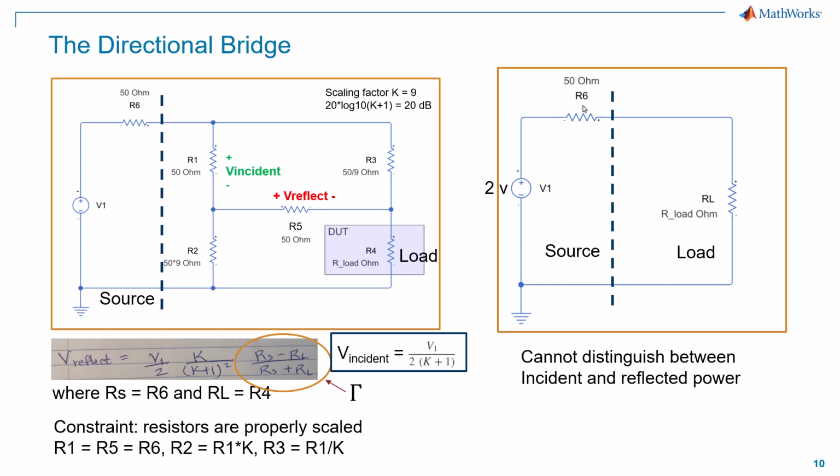It's going to be, the load will appear exactly like the load on the right without the bridge. So if source and load are 50 ohms here, and again, if we use the resistor scaling scheme I just described, it's also going to appear like a 50 ohm source and then 50 ohms from the source to ground again. So nothing has changed with regard to how the source views the bridge, bridge or bridgeless, in the case of the bridge balance state.